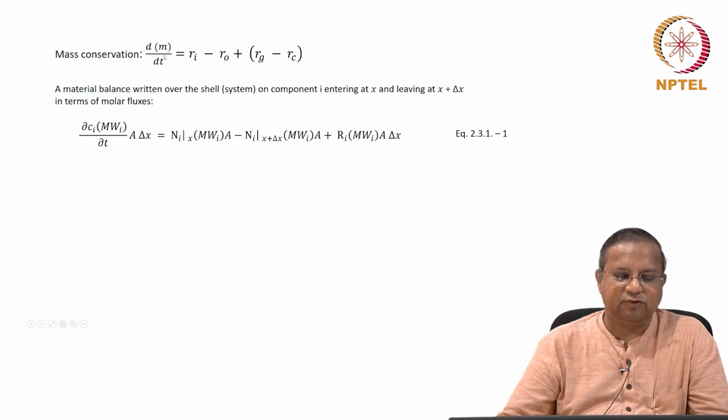The idea here is to get mass per time for each of these terms, and therefore, we took whatever we had, concentration per time, and we converted that into mass per time by multiplying by the molecular mass and the volume here. Here we had a flux, the molar flux, we converted it into mass flux first and then mass rate, and then similar thing that we did here.